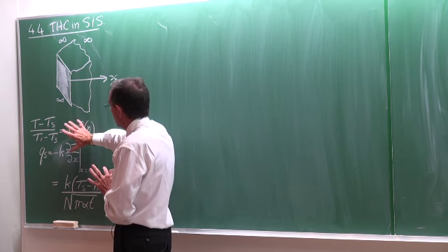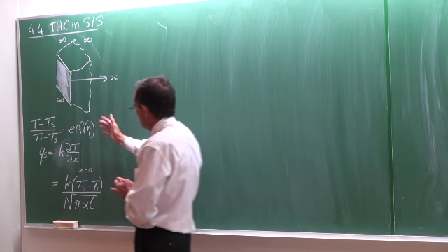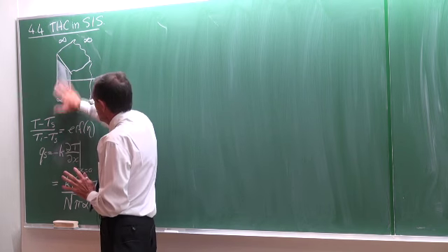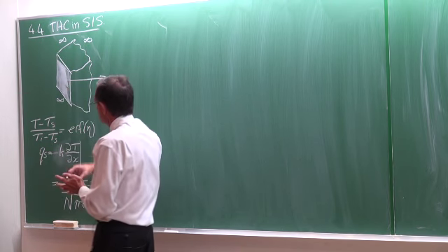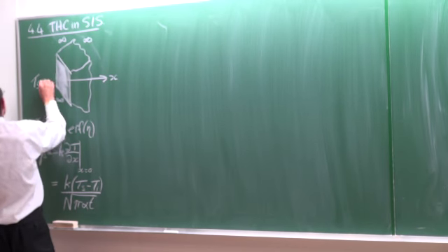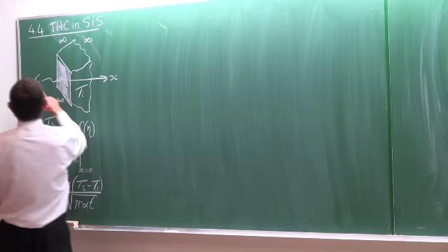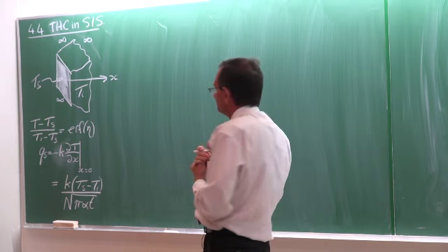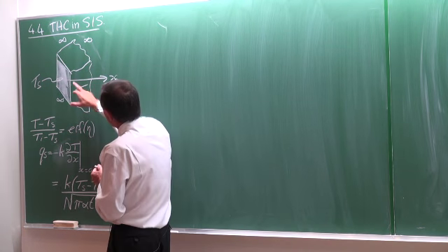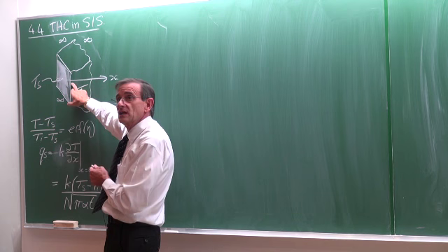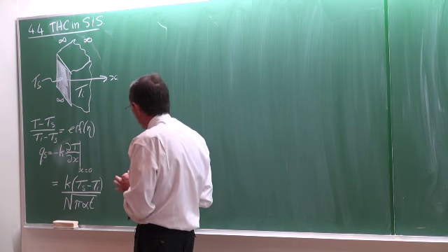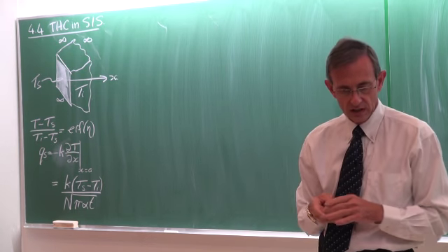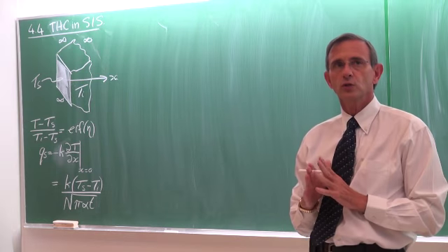Now with this, we've also derived an equation, typically like that, for very specific boundary conditions. This boundary condition was specifically if this temperature, suddenly at t equals 0, would change to Ts, while the rest of the temperature in the body remains constant. And since we can get the temperature gradient, we can also get the heat flux, and that was the equation. So let's continue with the rest of this part of the work.